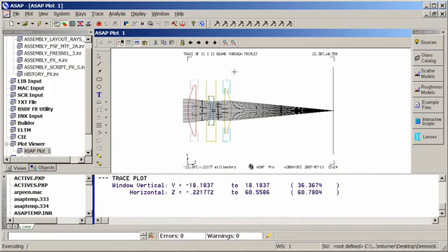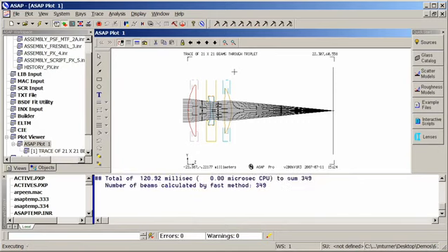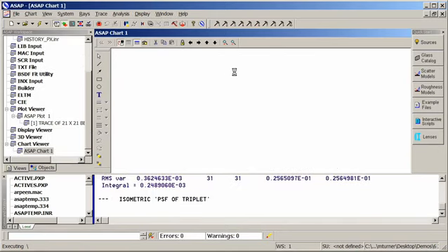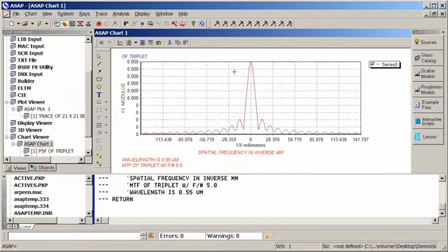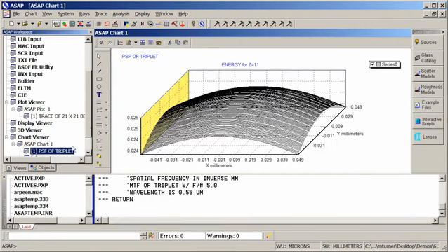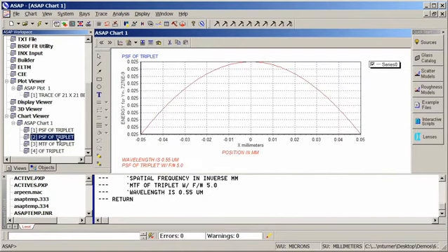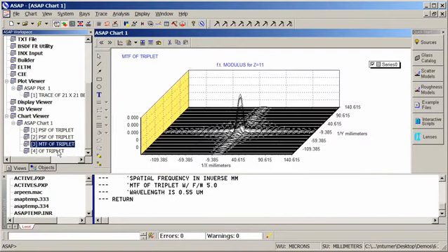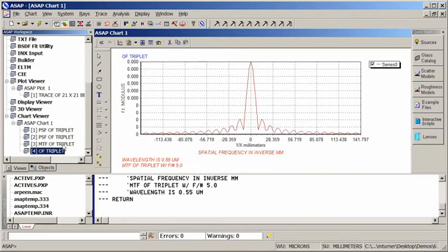We're going to do our analysis for an on-axis field point, so we're propagating a 21 by 21 set of beams through our optical system, and we're looking at both the point spread function as well as the MTF information. And here's the point spread function data, and here's the MTF information. And what we can see with the MTF plot